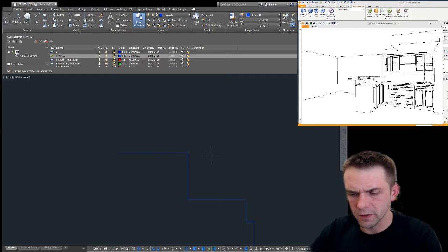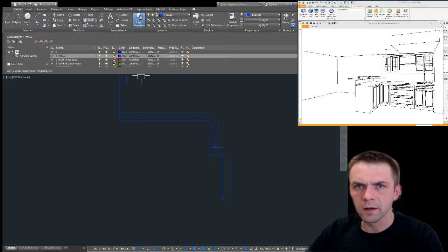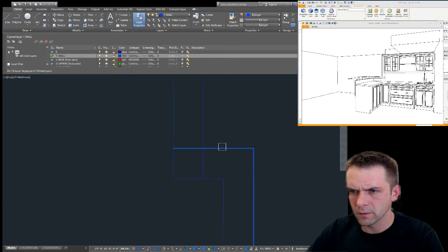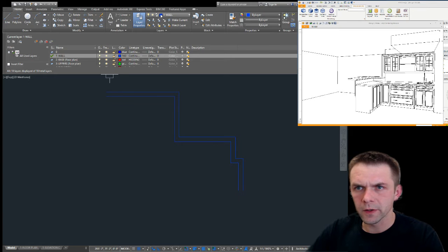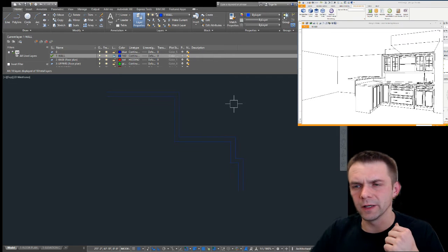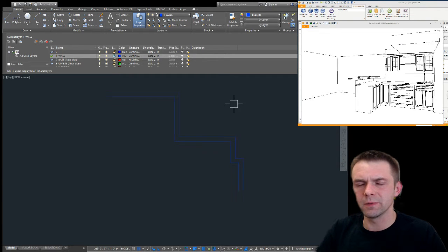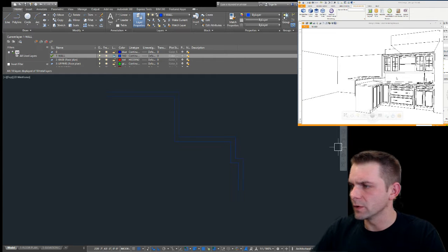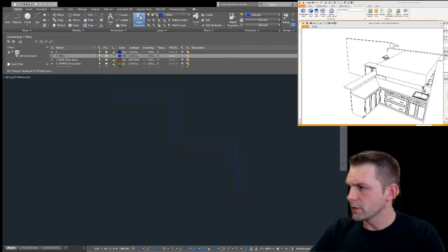I usually offset this 6 inches. And this way, and then we do a fillet. Okay, so we got our base figured out. What we do, we select and we lock the layer. Very, very important to lock the layer, because the more you work with different layers, the better it is to notice and to see and keep things organized. And then if you want to switch something, you can always turn off a layer very easily. So we see roughly how the drawing looks like.